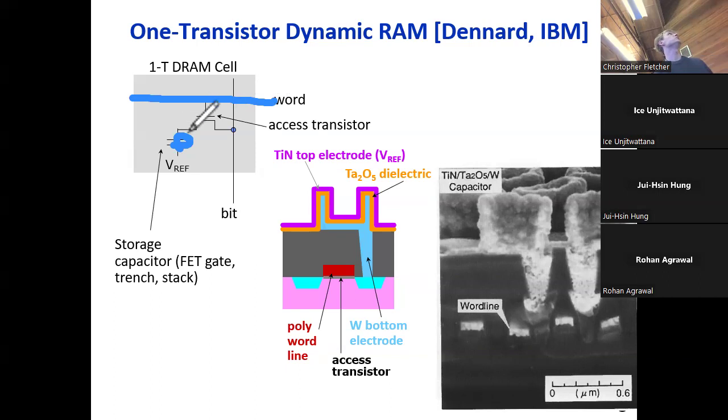And what that's going to do is turn on the access transistor, because this is an NMOS where the circuit is closed if you apply 1 to the gate. That turns this into a wire, and it allows the charge that is stored and slowly discharging on this capacitor to dump out onto the bit line.